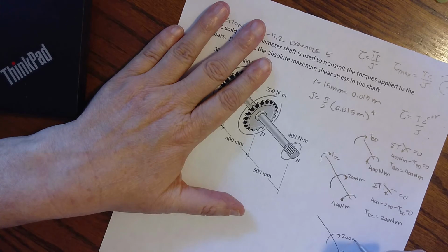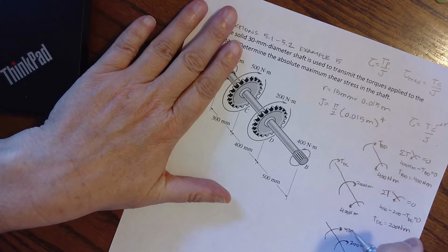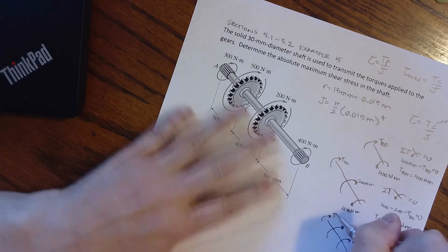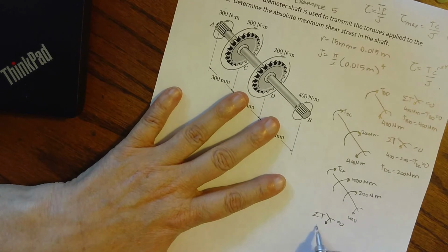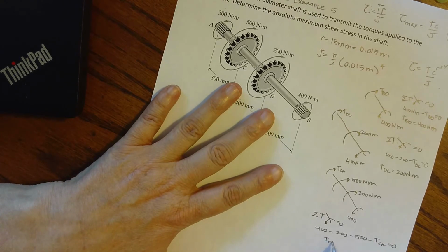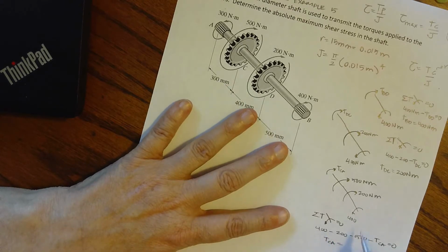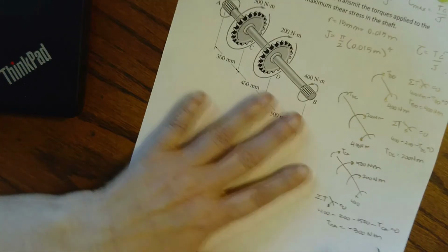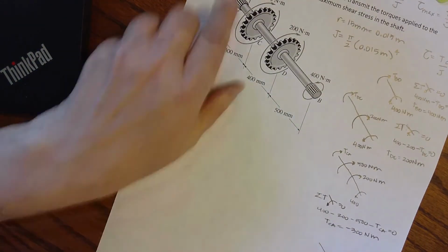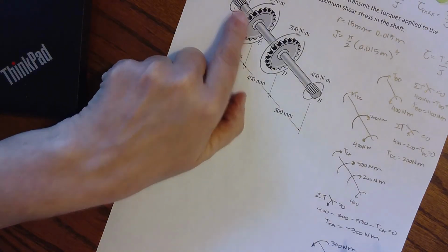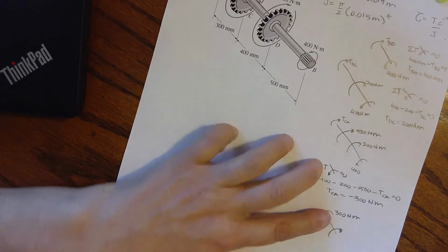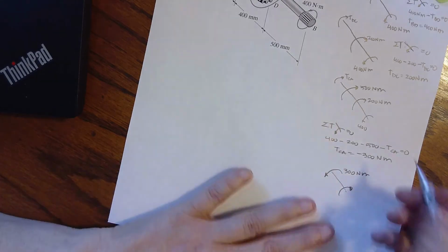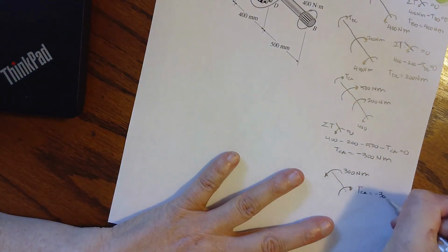So we have 200 Newton meters, and we have 500 Newton meters. And then I'm going to assume positive torque from C to A, and I'm going to sum those torques. That's going to be my positive reference. So I have 400 minus 200 minus 500 minus torque CA equals 0. So torque CA equals, take that over, negative 700 plus 400, so we get negative 300 Newton meters. How could I check? Well, I could check that by coming back from the back, where I have 300 Newton meters. I can visually see that the internal torque has to be going in that direction. By the right hand rule, with the butt of my hand going toward that end, coming towards me is positive. So I can see very clearly torque CA is indeed negative 300 Newton meters.